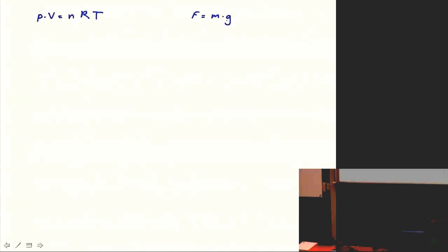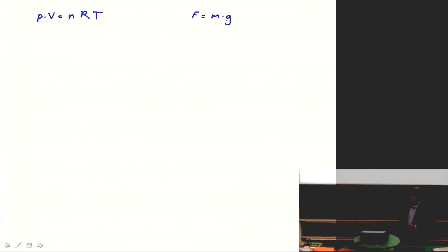So we normally want to look at certain points in the flow. Even if we study 1 cubic meter, we still have a problem when this air moves over the wing and we want to study smaller parts. So instead of volume and the number n, we would like something else that gives the state of the gas at a certain point, or at least for a very small quantity, like air density. So instead of volume and n, we would like to have air density. So let's change this formula.